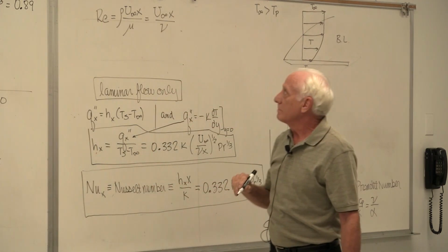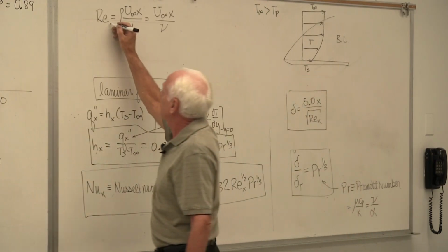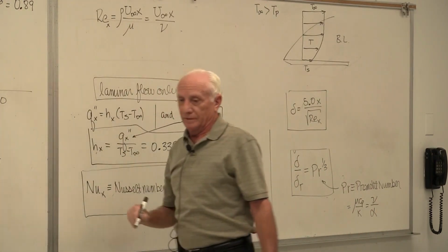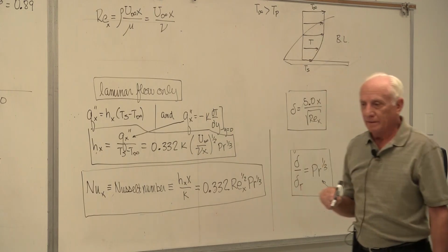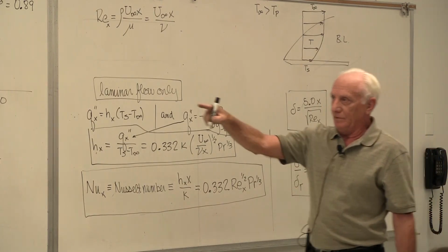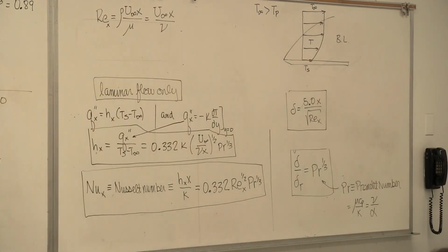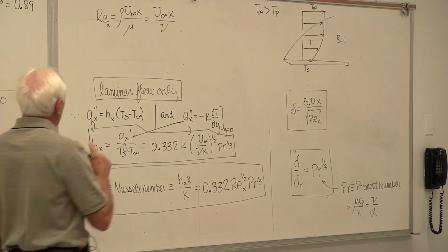Okay. The magic Reynolds number, if you had MA312, this is not a pipe. This is not 2,300. That's a pipe. This is a flat plate. Probably MA312, yeah. 5 times 10 to the 5th, magic number that we'll use.